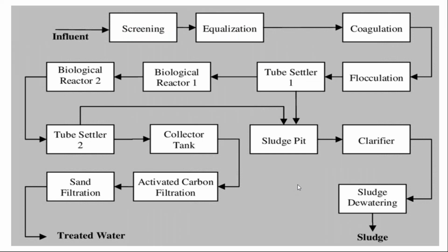So in general, when we are talking about the effluent treatment plant, this is the general flow chart which is accepted by all types of industries and by the designers or professional people who are going to design these ETP setups. This is the influent, that is nothing but the input of the trade effluent. Whatever liquid or wastewater is generated by the industry is the influent for this ETP, right? Whatever the quantity and flow rate, we have to take care of all these parameters. We have to send this influent to the screening facility.